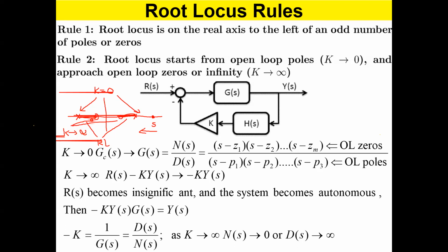And in this particular case, the entire root locus is what you already have here. 2 small segments. Now, if I write this, k goes to 0. When there is no feedback, k equals 0, closed loop transfer function is equal to open loop transfer function. So you have a numerator and the denominator for G(s). They are both polynomials of s, and you have these open loop poles. You solve this denominator polynomial equal to 0 and calculate the solutions, and these are the poles. So they are open loop poles.